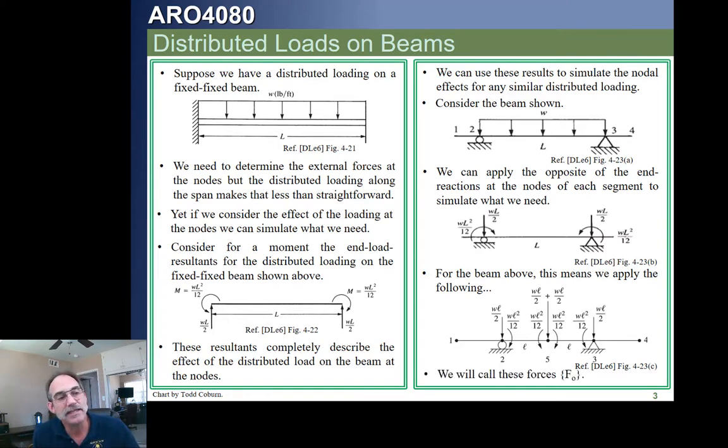What we're going to do now is, normally our force vector, capital F, has all the external loads on the beam. Parts of that F have the external loads and parts have the reactions. Now in this case, the only external load is one that we couldn't apply directly between the span. So the way we accounted for it was by converting it to an applied load. And these loads at the nodes are now those converted loads.